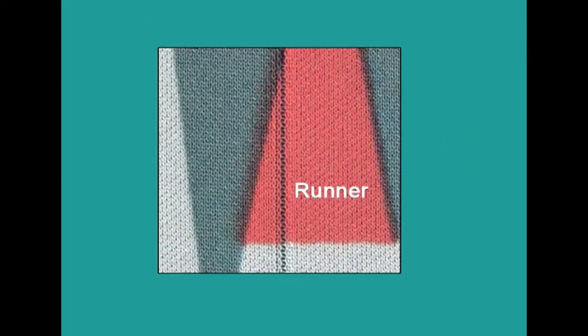And runners. A runner is caused by a broken needle, only seen in knitted fabrics. The runner will appear as a vertical line, and most machines have a stopping device to stop the machine when a needle breaks. It can be considered a minor defect if only one, and it can actually be mended with another needle.